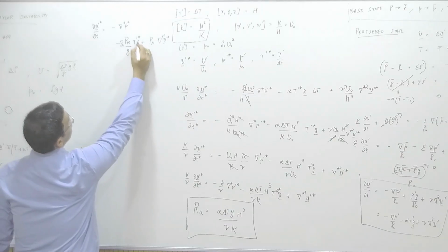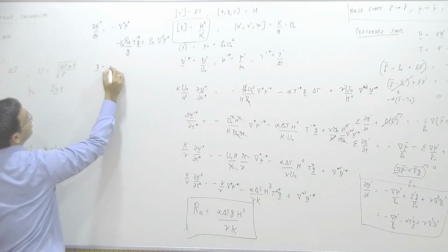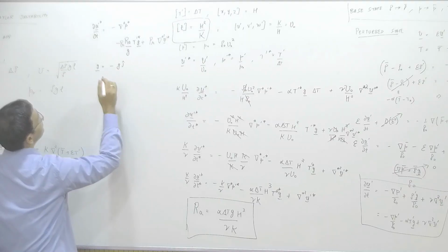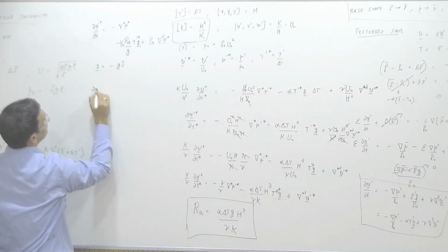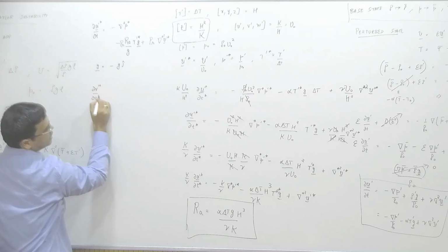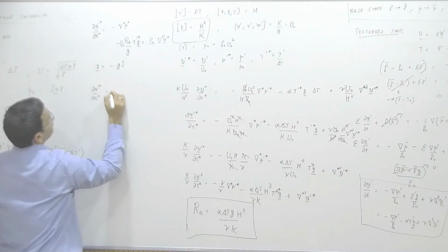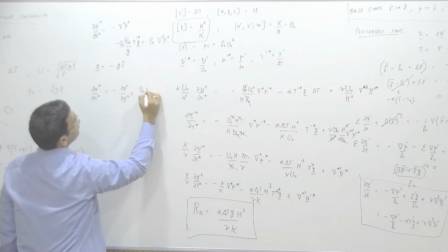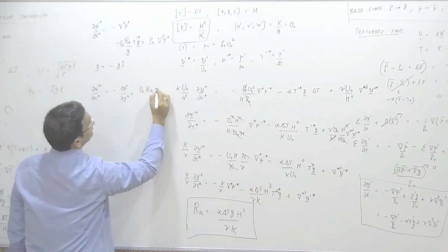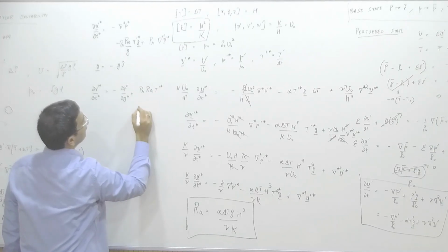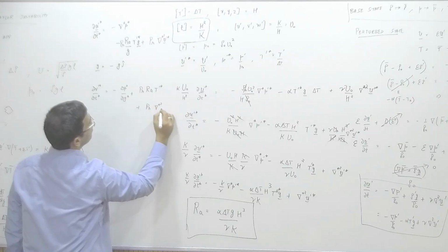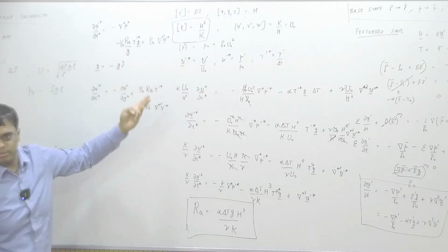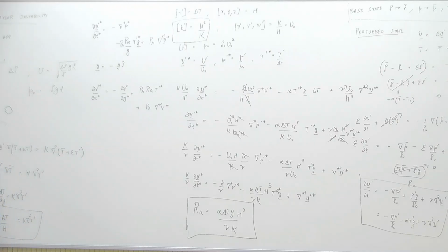So noticing that your g vector is just minus of g j cap, I can write the y direction momentum equation as simply like this. Okay, it is easier to write that. Plus Prandtl number into Rayleigh number t prime star plus Prandtl number del star square v prime star. Okay, for u prime and w prime you just won't have this buoyancy term, which makes sense. Also the buoyancy forces are only in y direction because gravity is only in y direction.